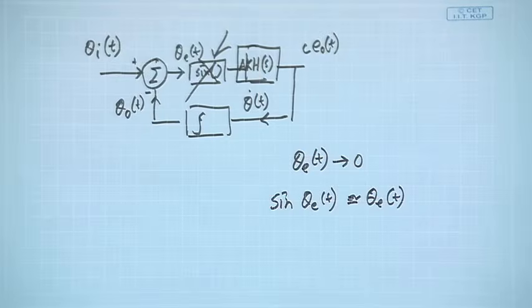So in the next class we will do this small signal analysis, or small error analysis, and try to see what kind of tracking is required. The only thing that is in my hand: the VCO is an integrator, I cannot touch that. All those constants I can change, but that will not change the overall transfer function of the circuitry. The only thing in my hand is the filter transfer function H(s). So we will see what kind of filter is to be employed and correspondingly what kind of tracking I get in terms of frequency and phase.